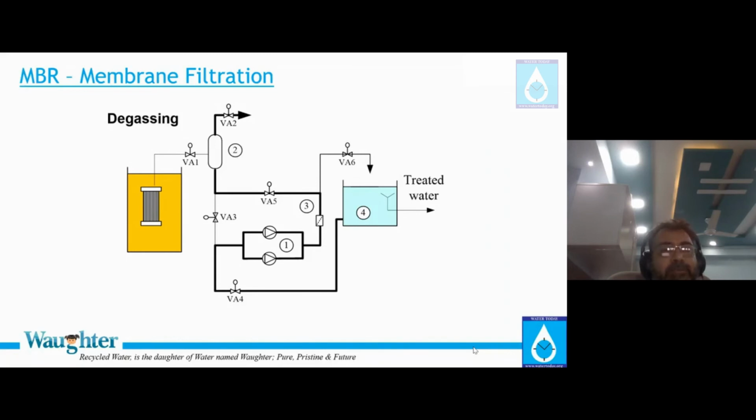And why is degasification important? That's the next question. When you look at the membranes, what are they trying to do? They are sucking the permeate. When they are sucking the permeate, can this ensure that they are not sucking any CO2? The answer is no. They will suck. As per Henry's law, because there is a vacuum in this particular line, a lot of air, oxygen, and carbon dioxide, everything will be sucked into the membrane fiber. When it is sucked into the fiber, then it will be deposited in the entire extraction line somewhere.